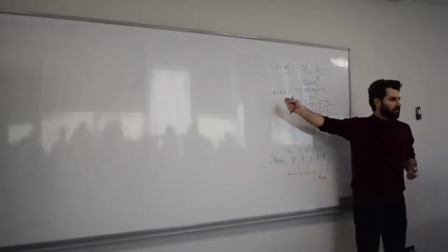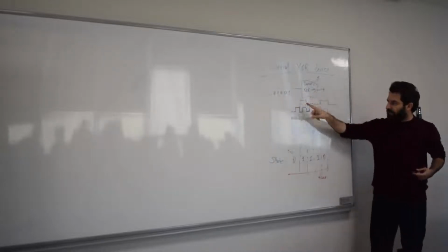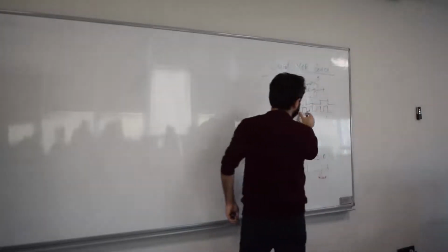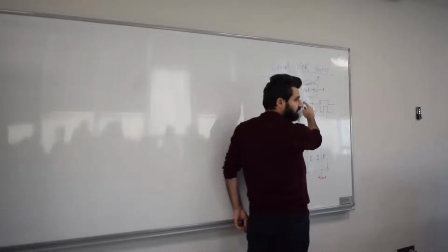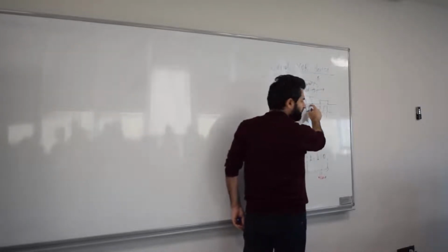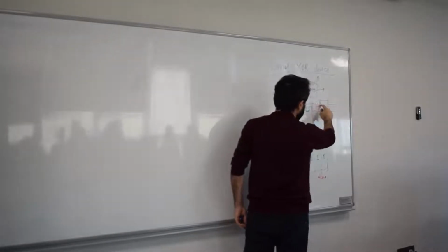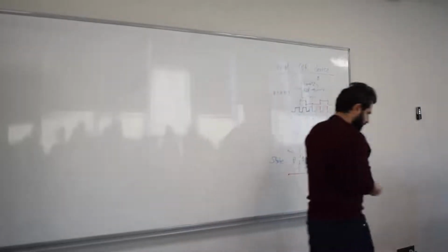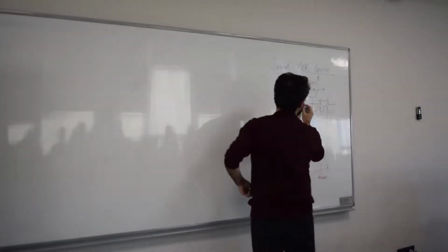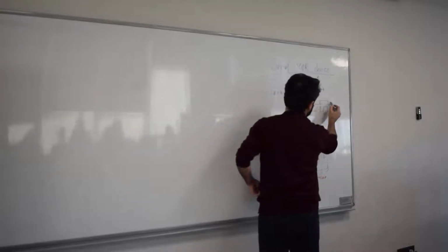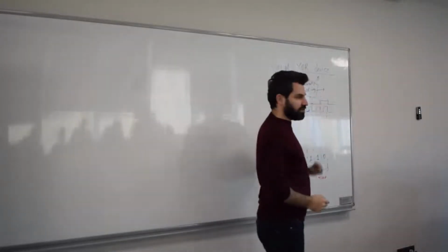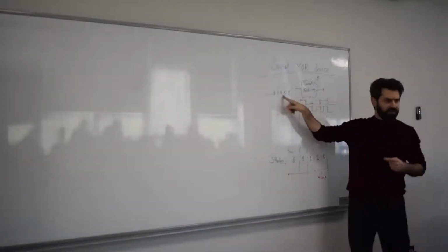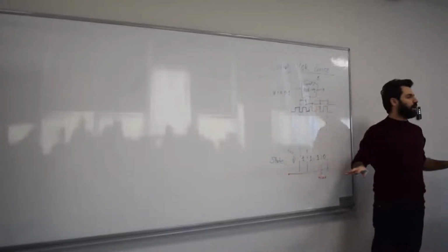The only requirement that you impose on this input is that it has to be synchronous with the clock. In this specific period of time, the voltage level here does not change. And for this period, it does not change, it's just 0. And then this is 0 again, and this is synchronous. You don't see something like that. If I draw it with another color, you don't see something like this either. That's not valid because that's not synchronous. I want a synchronous signal. That's the only requirement on this input, and other than that, you don't have any other requirements.